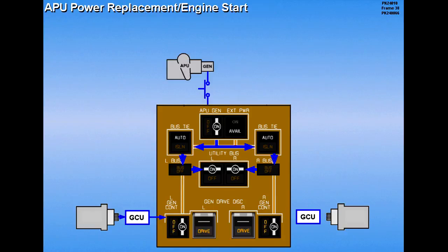During an engine start with the APU supplying power and the generator control switches in the on positions, the respective generator will automatically replace APU power when normal output is achieved. The APU continues to power the opposite system. When the second engine is started, its generator will power the respective system. APU electrical power is still available if needed. However, the APU generator off light remains extinguished.